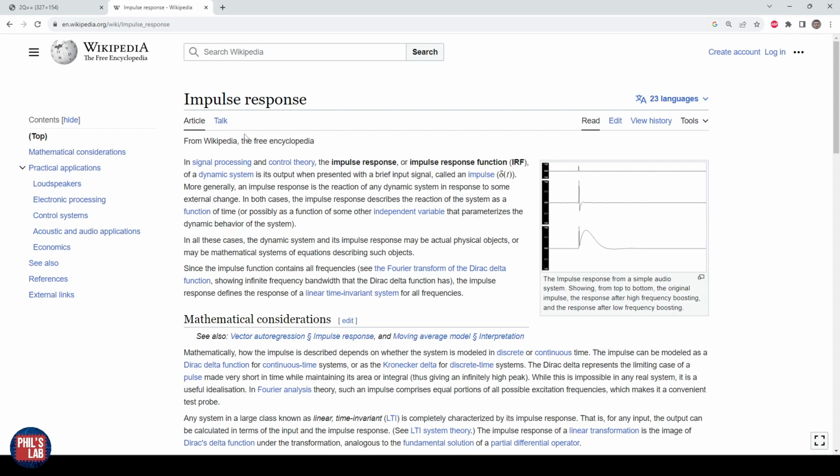However, guitar cabinets and pretty much anything in the real world is non-linear, so the impulse response does not fully characterize the system for a real-world system. Depending on what power level we input, what voltage level, where we place the microphone, and so on, we of course get different impulse responses, which makes it a non-linear system. For now, we'll assume just a single operating point, so a linear time invariant system. For a given impulse response, we get a given output response, and that's volume independent.